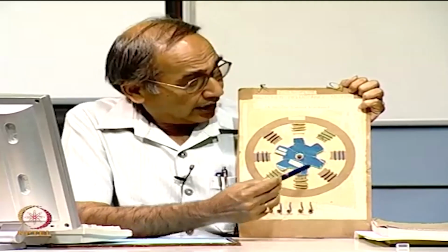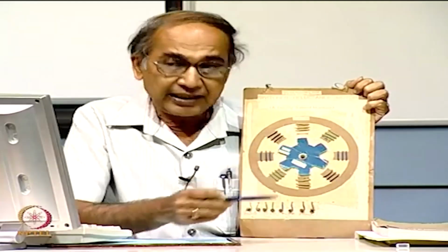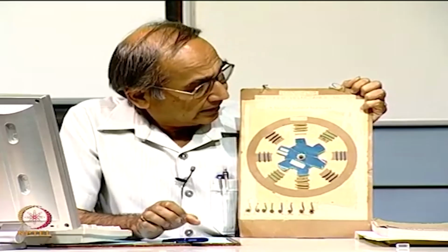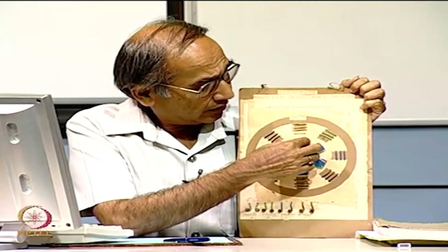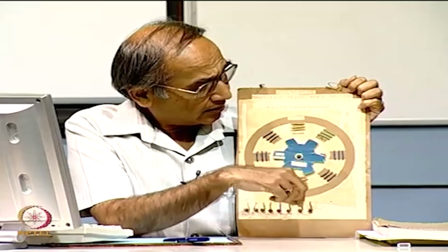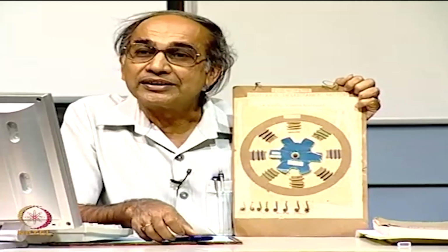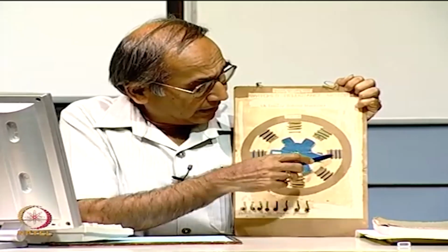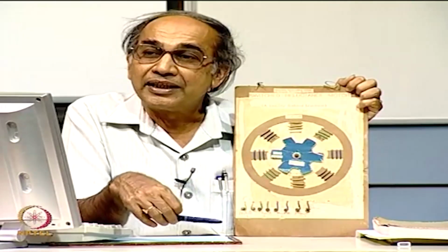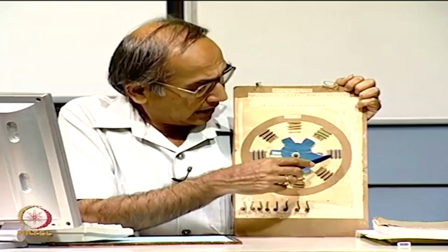Now, you tell me what will happen if the green coil is excited now. The green coil is excited, rotor will try to align with that green coil, isn't it. So, the green coil is here, so it will move like this, right, rotor will align with it. Now, if I excite the blue coil next, where will it move?